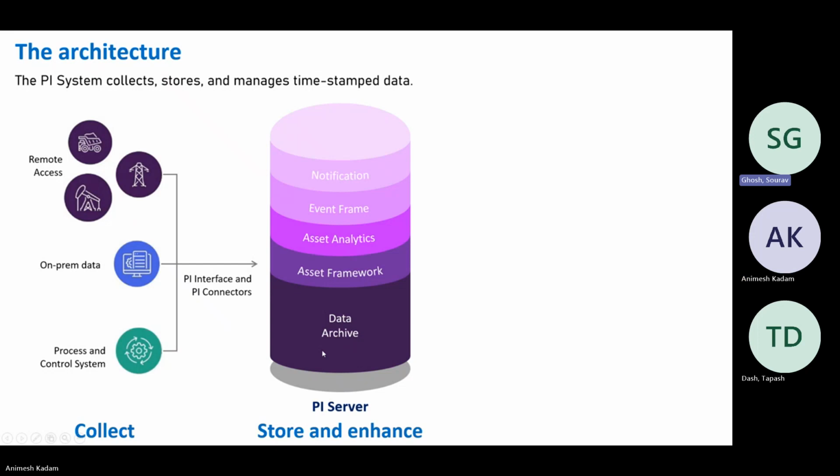Yeah, that's something I understood. I'm just thinking about this asset framework, the template. Forget about the data archive. This part I understood, that the data archive is not in the SQL, because that's huge data. But when it comes to SQL, you are saying that from asset framework till notification, whatever the configuration, let's suppose I have built a template. The configuration of that template, like how many tags will be there, where will it be stored? Everything is in SQL.